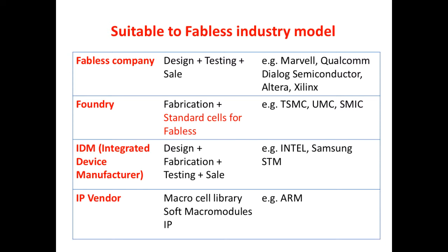Okay, you can buy from ARM a gate level design of a microprocessor, and you put it in your circuits and do the placement and the routing of all the gates. And the other possibility is that you buy the macro cell of a microprocessor for some specific technologies already completely designed. So with already the layout done.